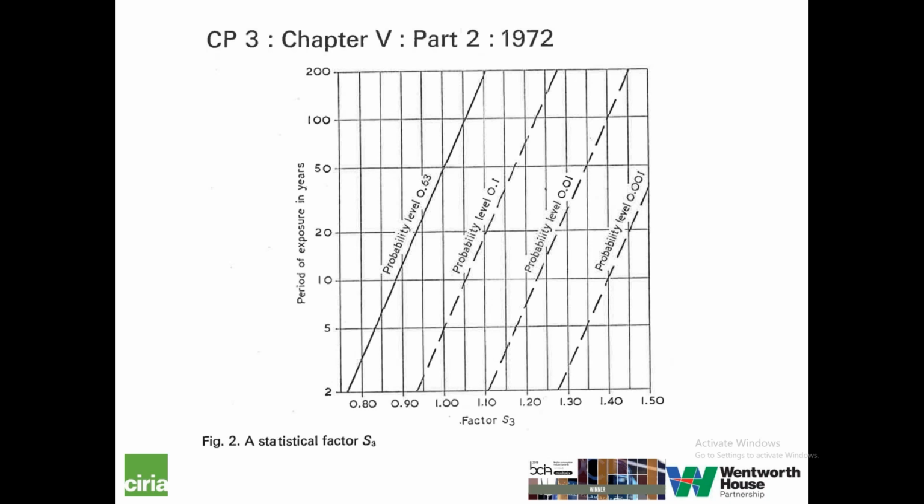We no longer do that, even in general. There are some items of temporary works which do attract a reduction factor in wind loading, such as hoardings. You may refer to the Temporary Works Forum's guidance on the design of hoardings and some scaffold structures. It's still not as low as 0.77, but there is a reduction factor.